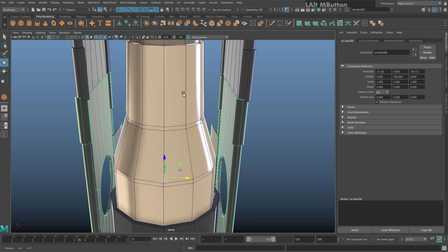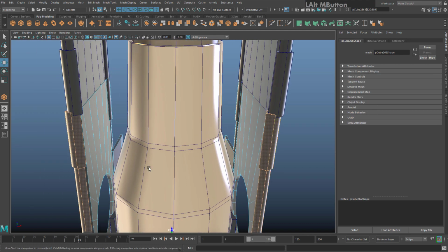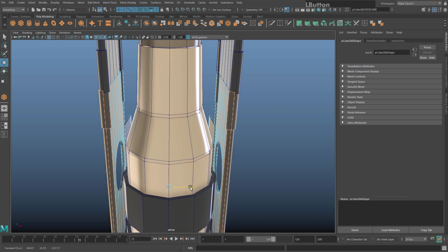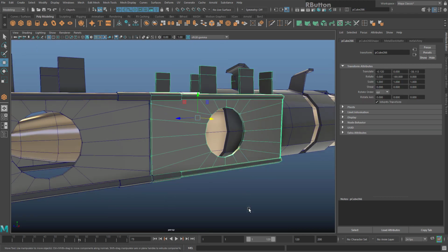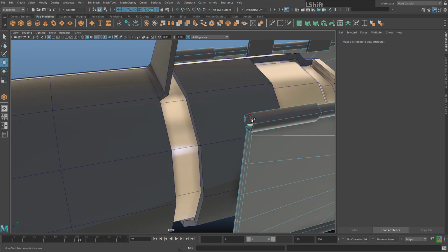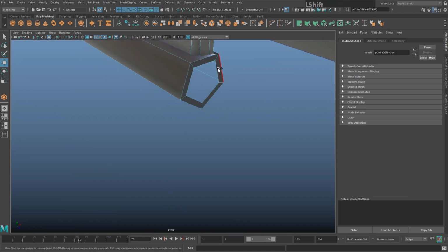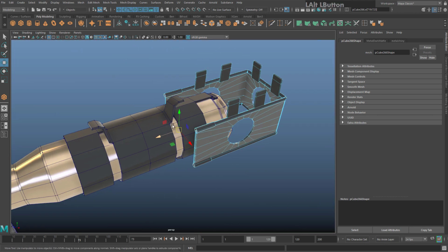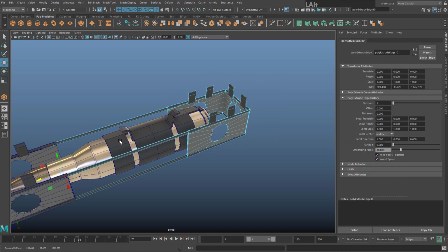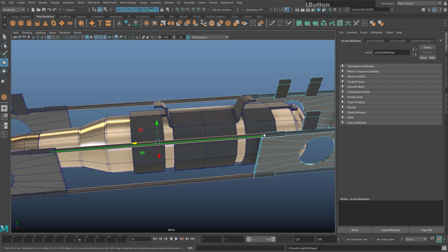That's looking good. Now the bottom ones don't. If you want to move geometry while it's combined, you can just double click like this, and then just move the faces of it while it's combined, and it plays ball. So that's good. And you can now move that back to there, and then go to edge mode and select these guys in the middle, these guys in the middle, these ones, and these ones. Do W for move, hold down shift, extrude those out to there, and you just need to go to edge mode, drag select them, and soften those edges out.